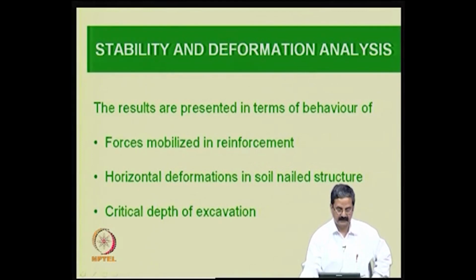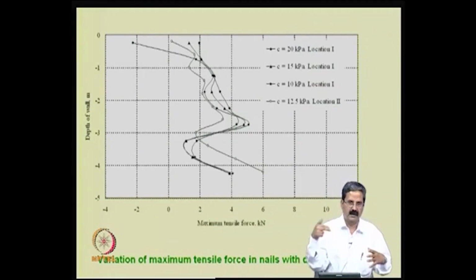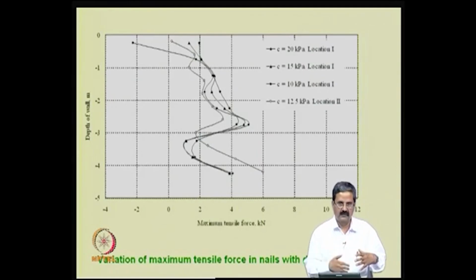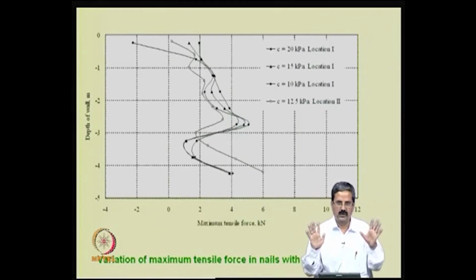So, once you do that, how do you understand the effects of construction here? Let us see that. In a numerical simulation, the way that we do it is you just excavate a bit and then put reinforcement, right. Excavate the soil and then put reinforcement. The same thing can be modeled in the numerical analysis, that you excavate and allow it to reach equilibrium, in FLAC or finite element analysis.